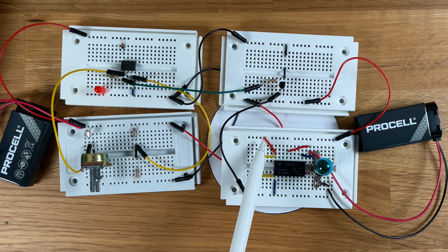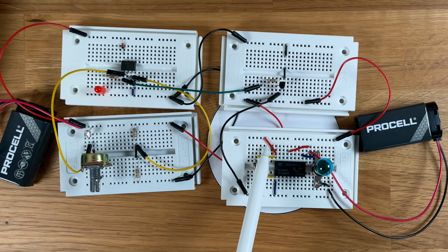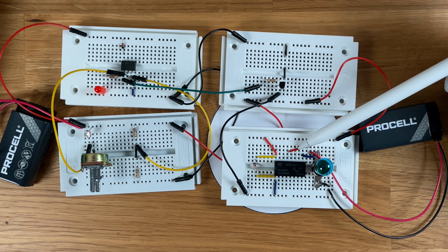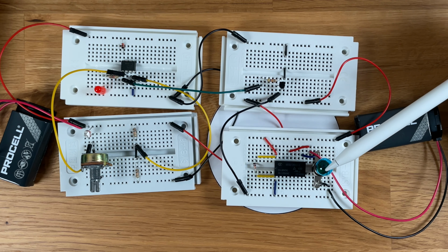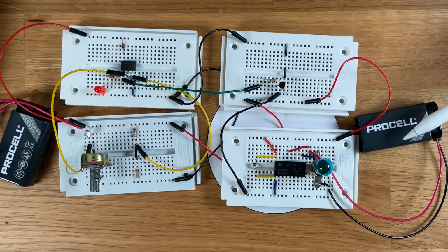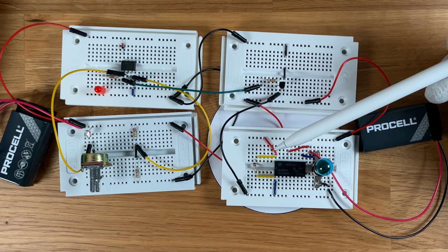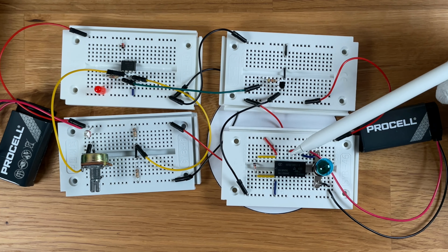We have the entrances to the relay up top, the red cable and the blue cable. This triggers this switch. A relay is nothing else than a switch, and it connects the red bridge with the blue bridge over here. In this closed circuit, we have the blue incandescent lamp, which is powered by a different battery. This illustrates the fact that we are switching between two circuits. We have the circuit on the left, we have the circuit on the right.